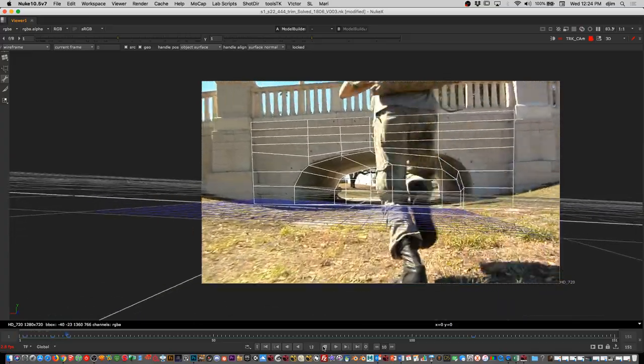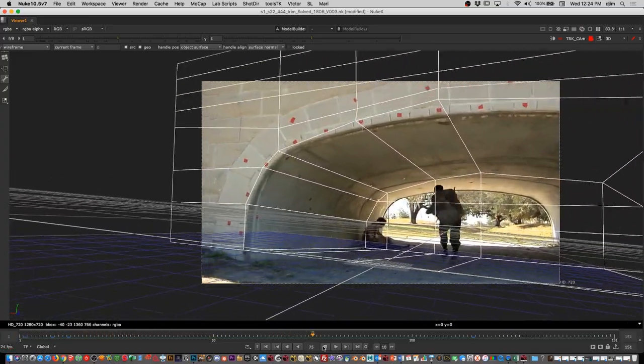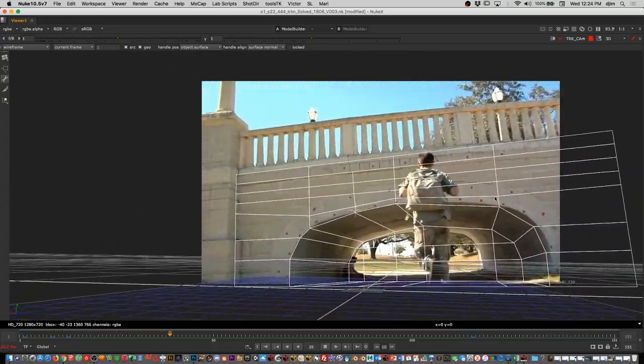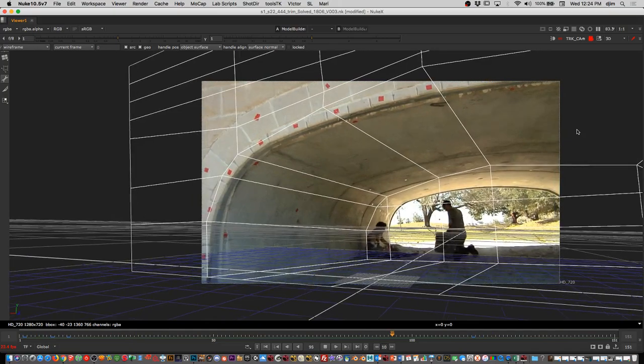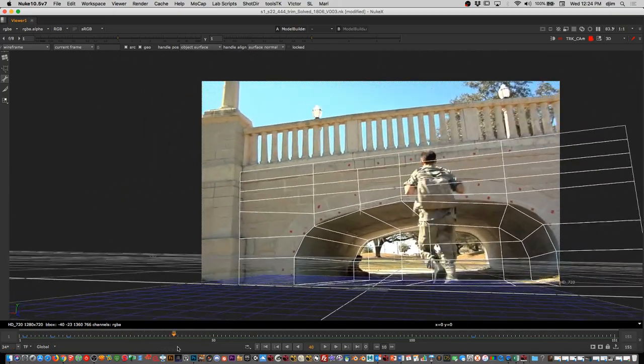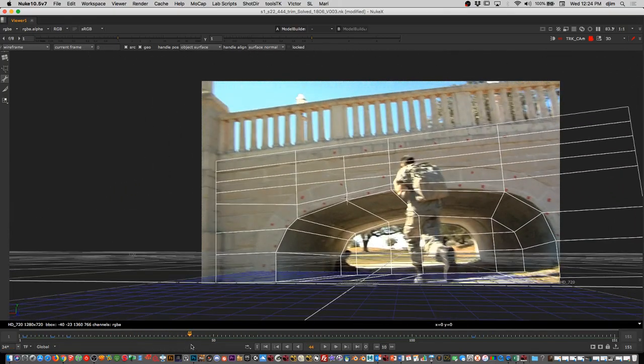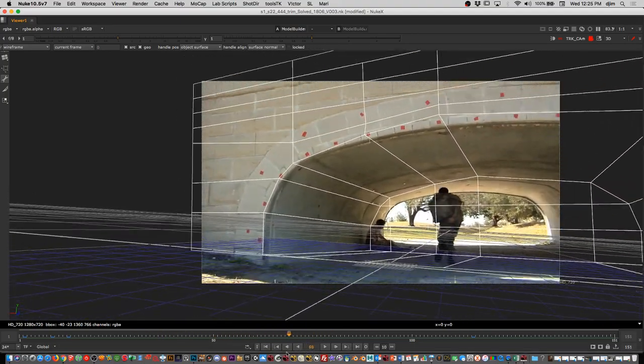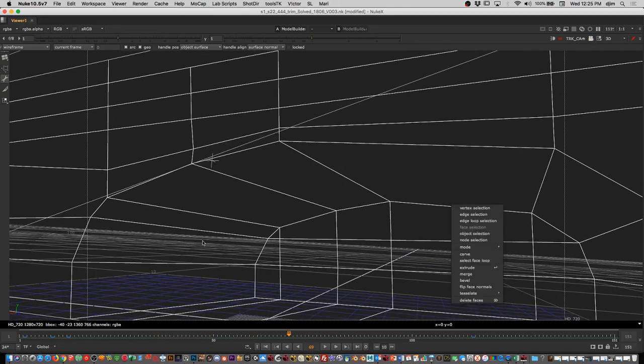All right, so it's cached now, and we see it against that. If it sticks, we're good. You see it's angled, because notice the right-hand side. Look how it slides faster in front of us. Right there, we know that our angle is too much this way. This side right here is actually closer to us than this side over here. So now you know, okay, I need to rotate this. I'm not using the point cloud data, so all that will help you immensely to do the job a little bit better. But that's pretty much an idea of how to approach that problem.